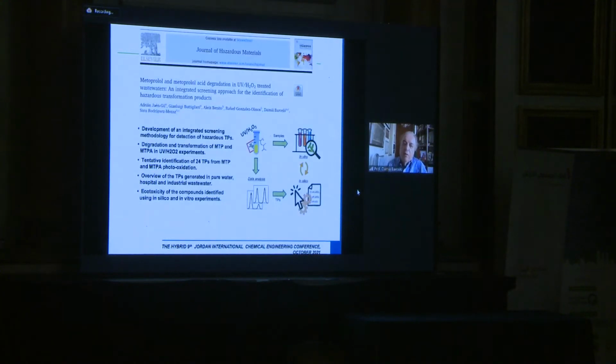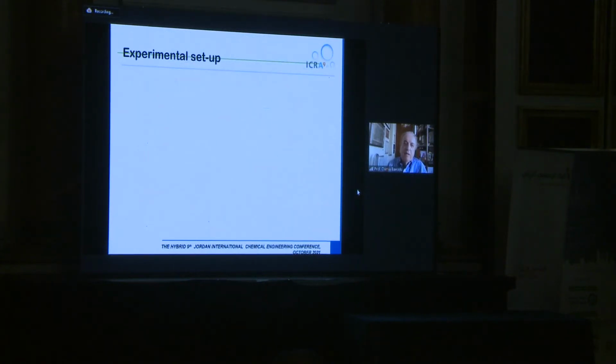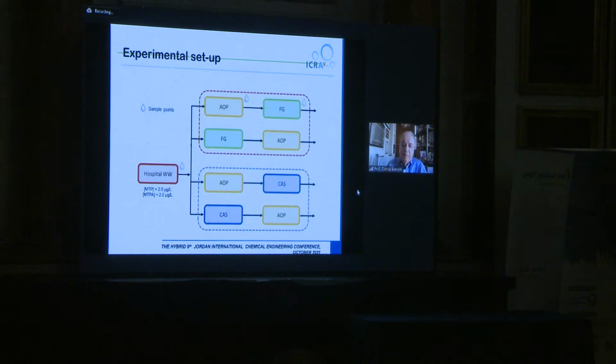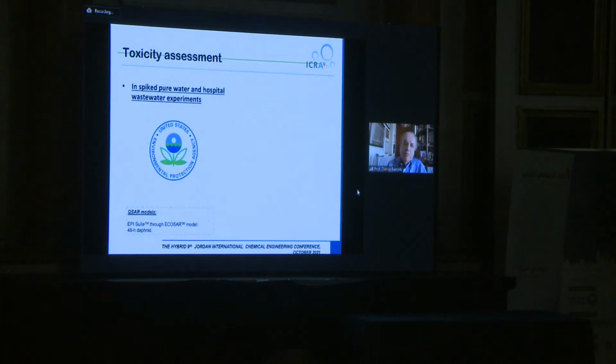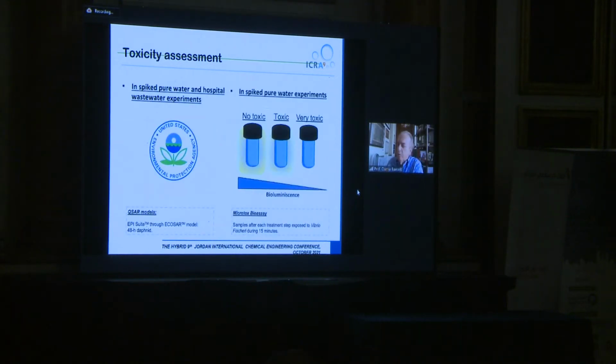So let's go now, in the same line, to more advanced oxidation and combined processes, like UV treatment, degradation with UV and combined technologies. In this case, we had UV and H2O2, photooxidation of the same compounds, like metoprolol, in the water treatment. We evaluated several combined treatments: advanced oxidation, fungi. We wanted to know which was the best setup for elimination of all these chemicals. This was also combined with toxicity tests because, at the end of the day, when you eliminate chemicals from effluents, you want to know if the effluent water is less toxic than the original water. Otherwise, there is a problem, you understand, basically.